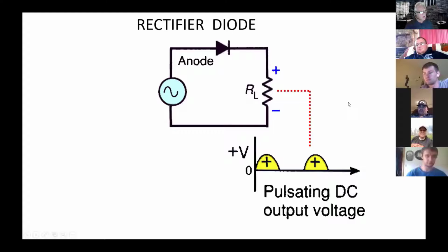An application here, the load, maybe this is your battery charger. So you've got a battery charger. This is your battery right here. You've got it hooked up positive to negative. And anytime that you're on a positive half cycle, you're pushing electrons into that battery to be stored. Now, if it weren't blocked, it would just suck them back out again on the next half cycle. But because it's pumping these in on every half cycle, that's what charges your battery. It's replenishing your battery with electrons.